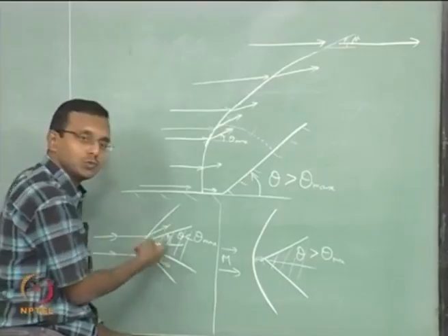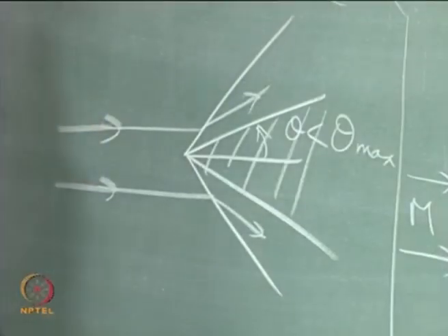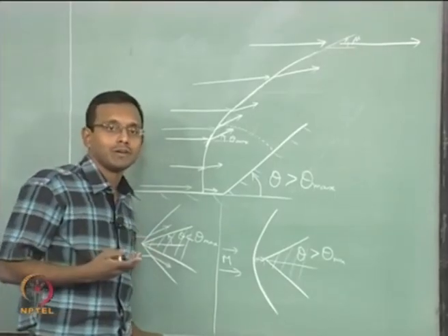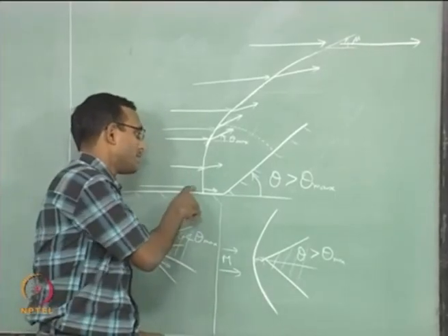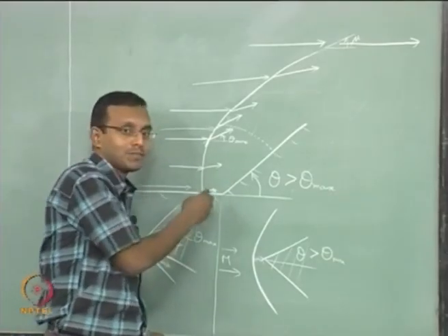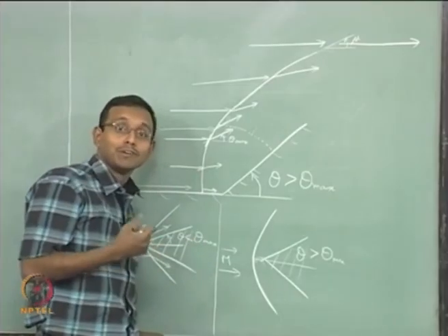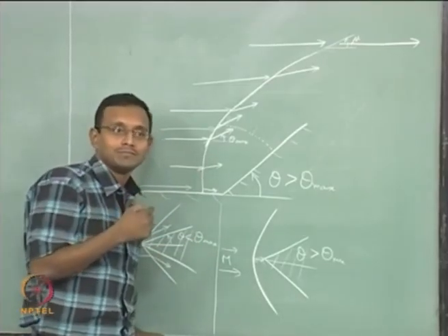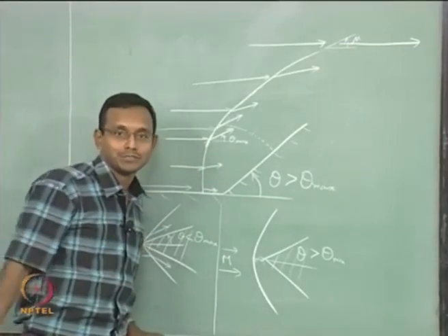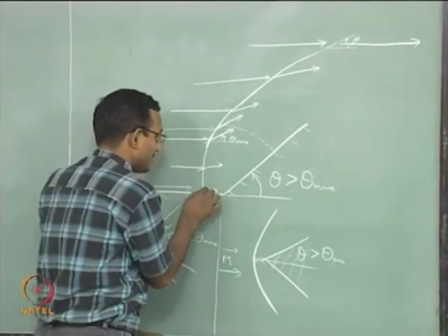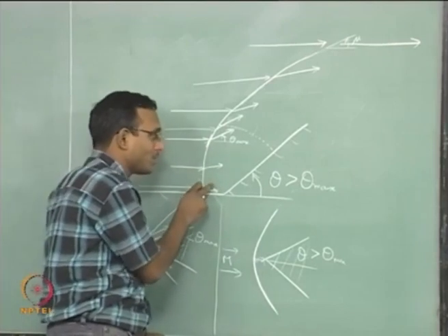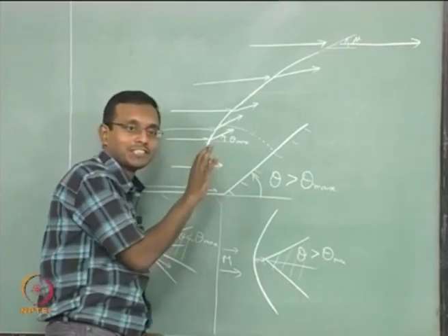If I had the change too strong, then it has to change very fast, which is not possible for a fluid. So what it does is, it makes the flow go subsonic, with a very slow velocity and very high temperature, so the speed of sound is very high and velocity is very low, so it will have very nice feedback in here to adjust to the situation. What happens is, after this the flow has become subsonic, and then the subsonic flow knows where the wall is.